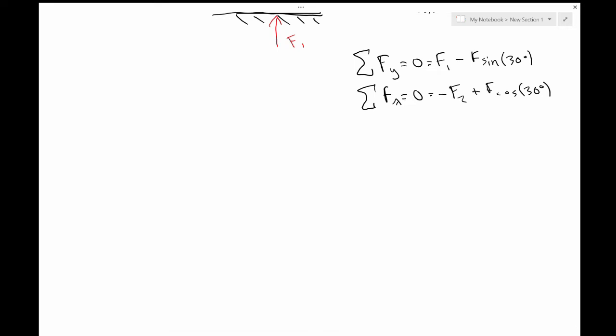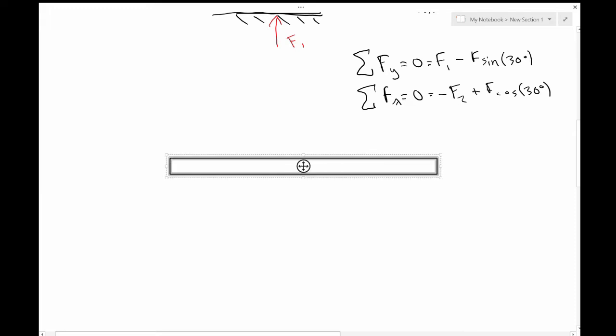But now let's say we have, draw another box here, and this one's going to be quite long. Its center of mass is going to be here, but we have a force coming here. We'll call that F, and a force coming here. We'll call that F1. And so we can see that, to balance out in the y direction, F1 is obviously equal to F. But from intuition, we can know that this object isn't going to be at rest, right? It's going to start to actually spin around the center of mass, around point C.